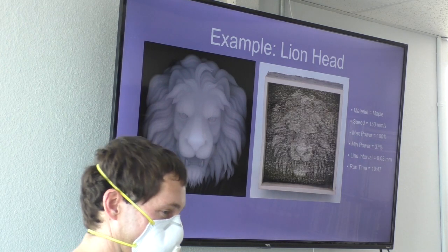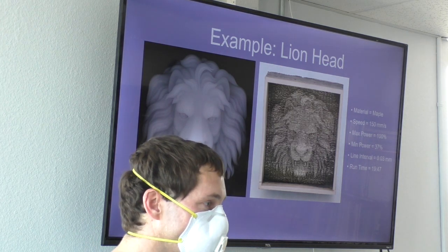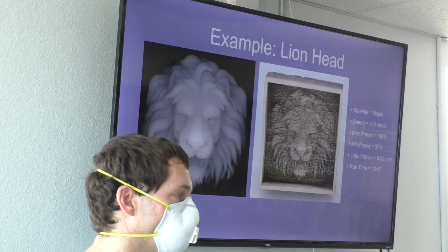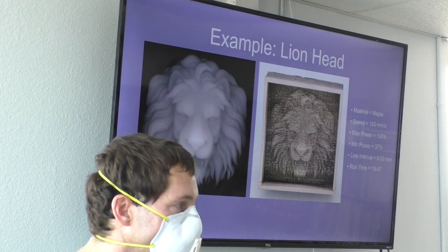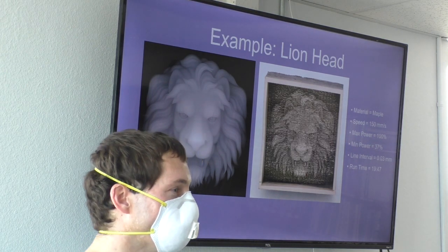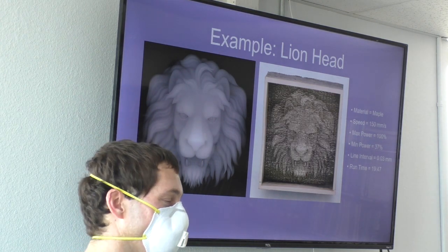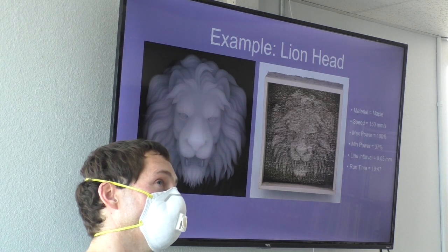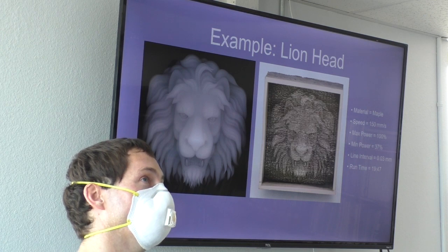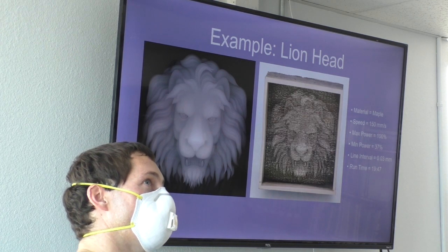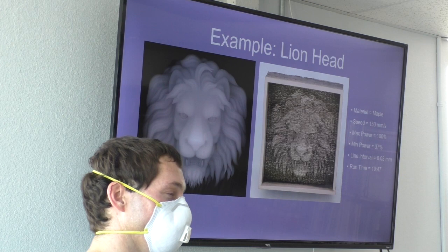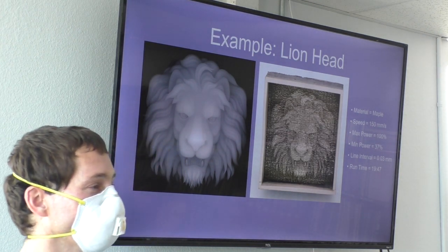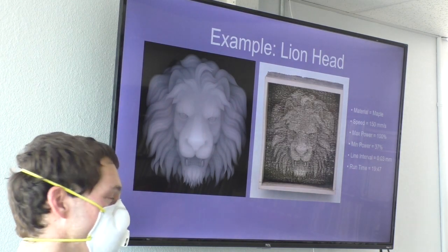So when you were cutting these thicker ones on the laser, David, were you just using the same Z height the whole time? You weren't varying it? Yeah, in fact, there's very little variation possible. There's only 5 millimeters to work with anyway. And if you drop it below 2 millimeters from the focus, the air assist is so powerful that it almost works like a plasma lance, where it's just abrading away the wood itself too. So it didn't work out very well.